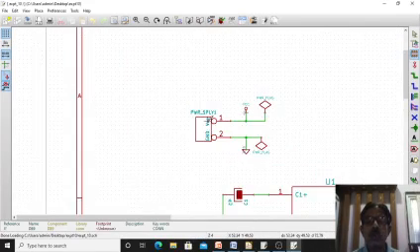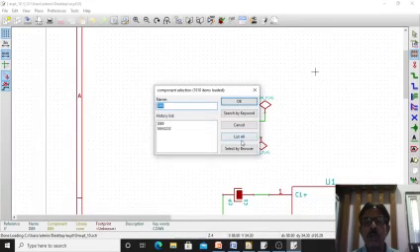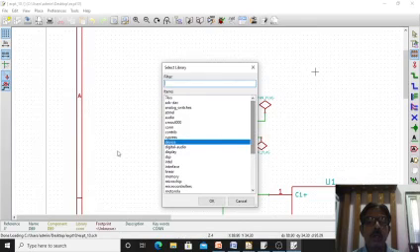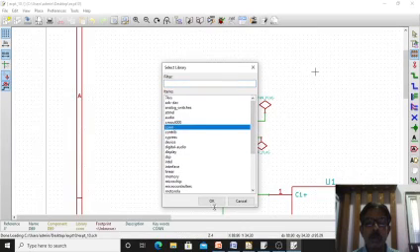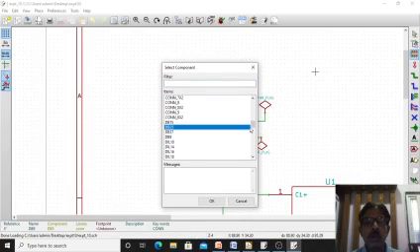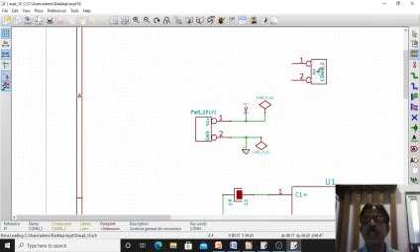I require 2-pin connectors. Okay, and already you know how to collect this 2-pin connector, that is this, then list all, then CONN, it is present in CONN. Okay, in this CONN you search for CONN2, that is connector 2, it is there here. Okay, you can take this. Okay, after this edit its value.